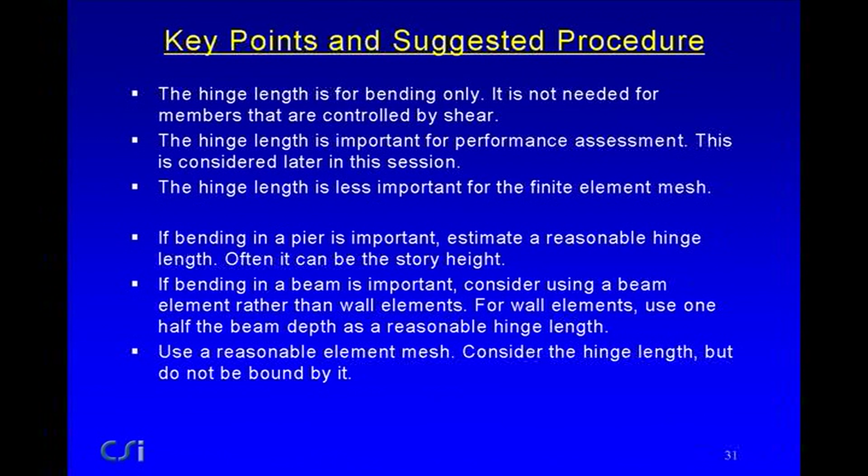So if bending in a pier is important, estimate a reasonable hinge length, and often it can be the story height. It's very nice if it can be, because that just gets around the problem.